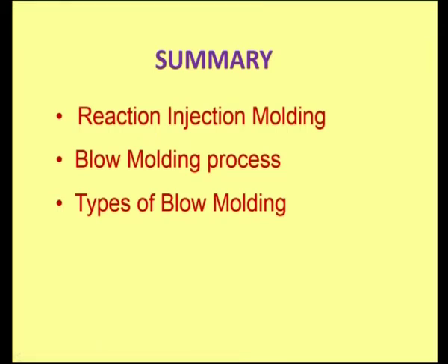In RIM we mainly prepare large sized parts. The septic tanks we normally find in an apartment, a big black colored tank, are normally prepared by the reaction injection molding process. One more variation is reinforced reaction injection molding, wherein a preform is placed inside the mold and the other things are as usual. The resin is allowed to fill and completely cure the preform, and then you take the product.